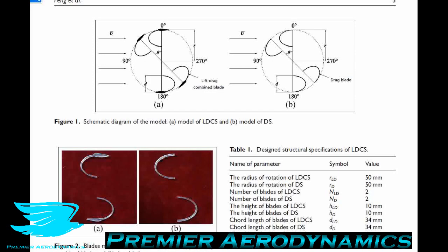At the blade tips, we now have these geometries, these airfoil profiles that produce lift. The air comes in and then the lift gets produced perpendicular to the direction of the airfoil. Now these airfoil profiles are uncambered, which means that when they are facing the wind straight on, there is no lift being produced, or at least very little lift, because there might be some interference from the rest of the blades, which might change the flow field a little bit and change the angle of attack that the airfoils are seeing, but ideally there is no lift being produced at this point.